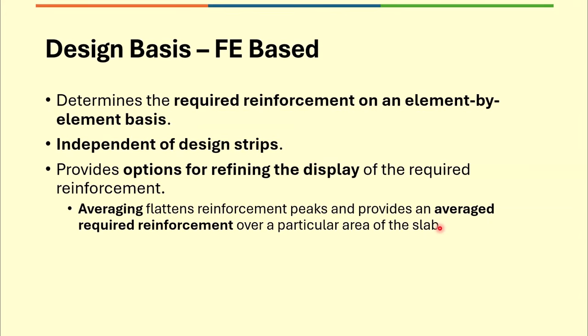You can use the finite element based output when the design strips cannot be drawn due to the geometry, the skewed nature or something like that. This is independent of the design strips, and it provides you an option with averaging for refining the display. So everything will be graphical output for this design basis.